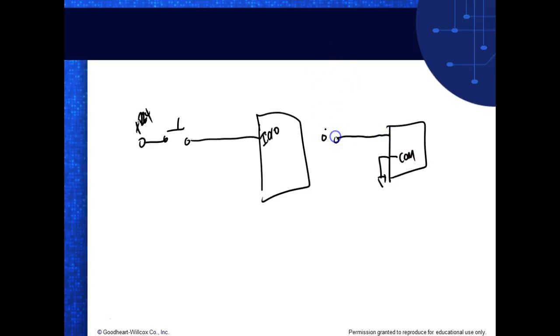Well, over here on this side, the switch is going to be hooked up, let's say, to plus 24 volts. Well, that means my input over here has got plus 24 volts. What is it looking for? It's looking for a common. Okay, so if this guy is hooked to common, it's sinking. This guy is hooked up to power, so it's sourcing.